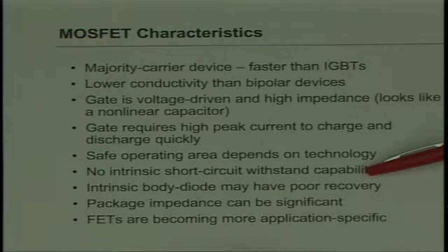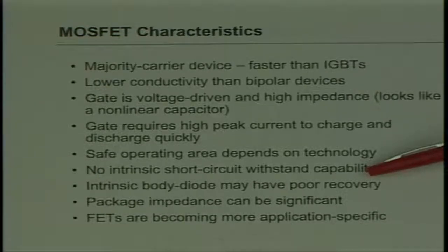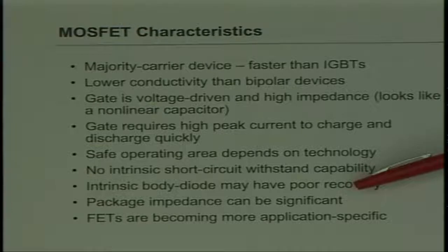FETs usually have no intrinsic short circuit capability. In other words, if you can turn it on, it will draw more than enough current to destroy itself. So you can't rely on the device to self-limit like you can with some IGBTs we talked about last week.